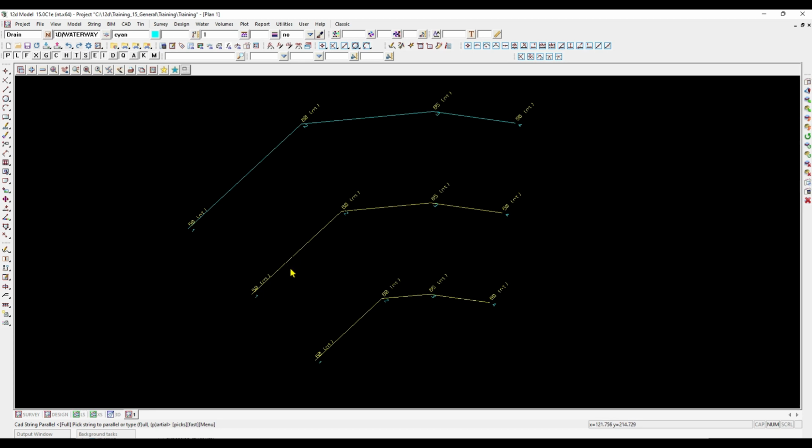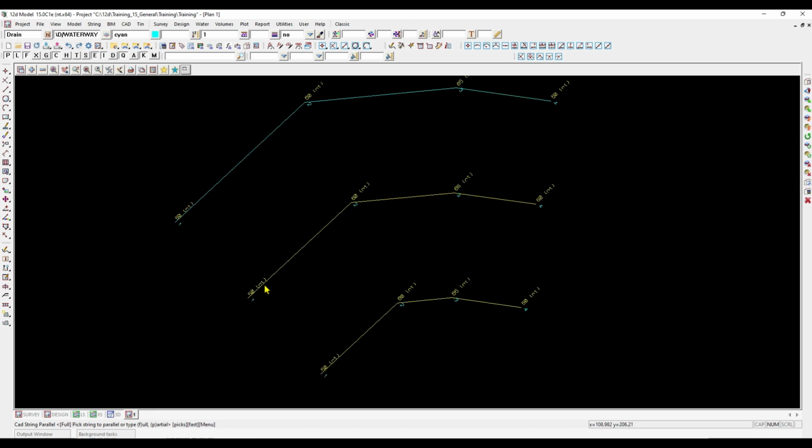I'm going to show you this in the negative numbers. So if I select the string from vertex 1 to 2, so left to right, middle mouse button accept, and I'll give it a negative number. Let's go for negative 20. Go enter and enter.